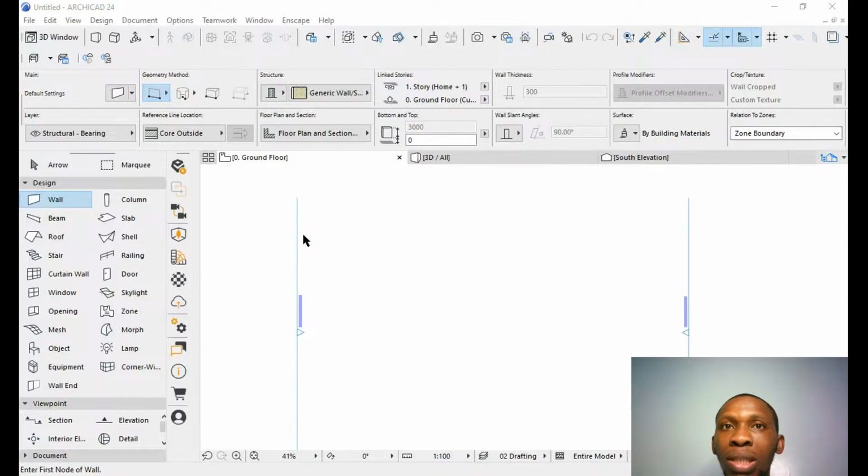There's a topic we talk about called architectural drafting. In drafting, you understand that there are different sizes of pens, and every line you see on your drawing means something. There's a way you can present it, make it look much more presentable, more graphically meaningful, right? This is where you come and do all those settings. I would have done it, but I'll just talk about it a little. You can select building plans, pen weights, and sets for structural engineer, mechanical, and so on.